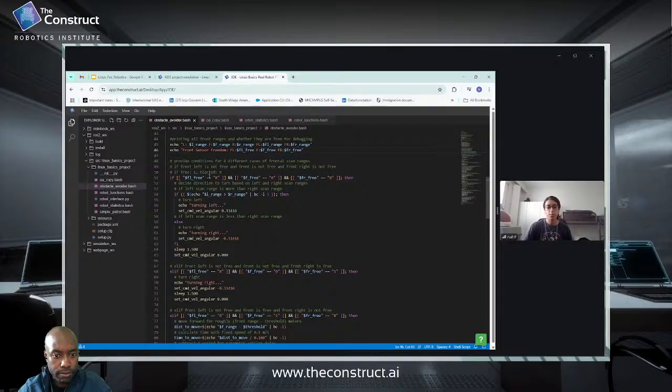Here are just 8 of the if statements. So there's 8 different cases here because I'm using the front 3 sensors to dictate which direction I'm using. And then if I want more controlled movements, I'll go to checking the other 2 front sensors, the left and the right. So here we've got the front left, front, and front right. And if they're all blocked, then we want to check whether the left lane has no leeway and turn right.